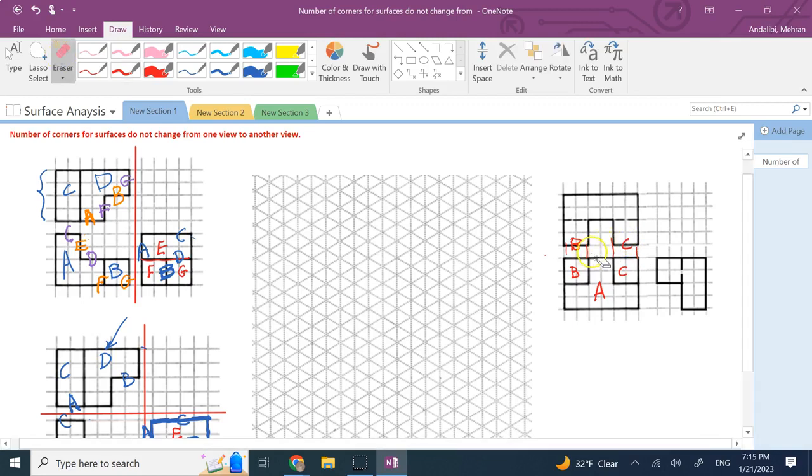What about A? Well, if I want to transfer A, it includes the entire width of the object. So it should be something that matches the entire width of the object. There are two options. What are they? One is this invisible edge here. The other one is the entire surface, this C-shaped surface.